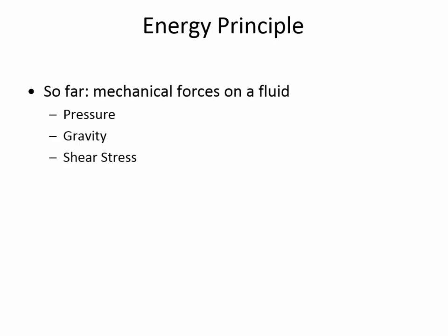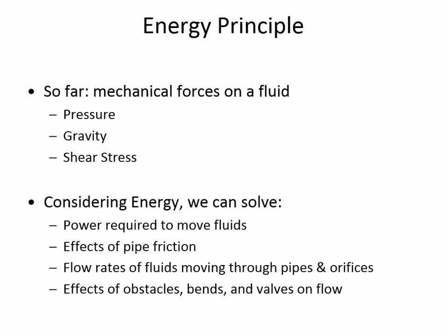Now, what we're going to be looking at in the energy principle is ways to account for losses as flow goes between 2 points. If you think about the types of forces that we've encountered so far, like pressure at a certain depth acting over a surface area, that was a hydrostatic force. The gravitational forces affect the pressure because they affect the depth, or the shear stress forces when we have an object moving through a fluid. When we start to consider losses, that opens up the range of problems we can solve, because in the real world, whenever fluids are moving, there are energy losses that have to be accounted for.